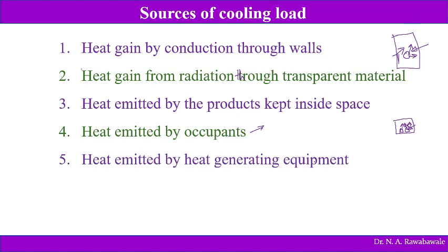Heat emitted by heat generating equipment. Say for example, when you are dealing with an air conditioning system, air conditioning is provided to a room. In that room there will be a lamp, a fan, a refrigerator, maybe a television. So many devices are working in the air conditioned space. Such devices emit heat energy, and that adds to the cooling load.